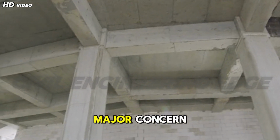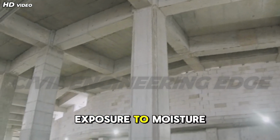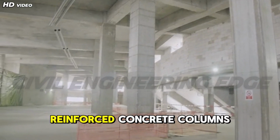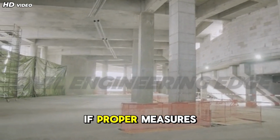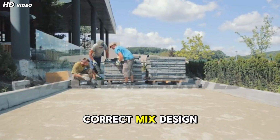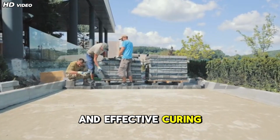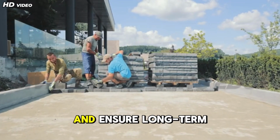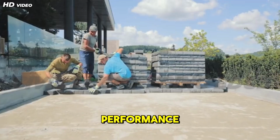Durability is another major concern. Exposure to moisture, chemicals, and temperature variations can deteriorate reinforced concrete columns if proper measures are not taken. Adequate concrete cover, correct mix design, and effective curing practices are essential to protect reinforcement from corrosion and ensure long-term performance.